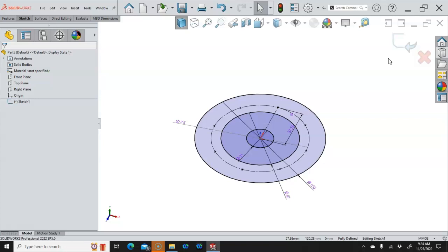I would leave this as a scaffold, an envelope, something that this sketch drives everything else. Pretty apparent that it's the first item, and when you look at it, all the dimensions are here. And then when you start opening up features and there's no real dimensions, it's kind of a flag that I used this technique.